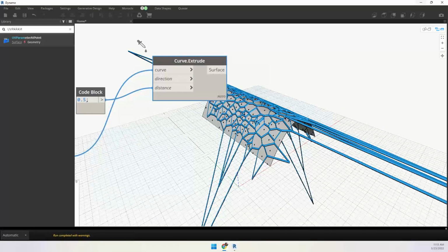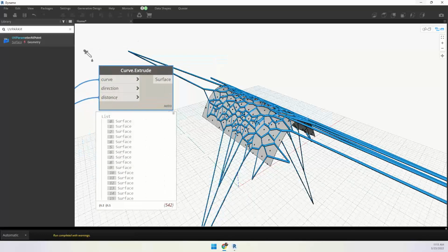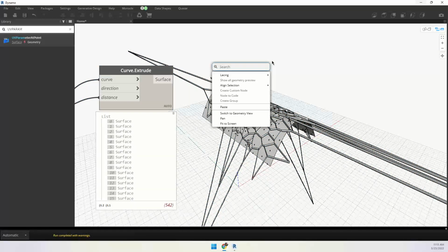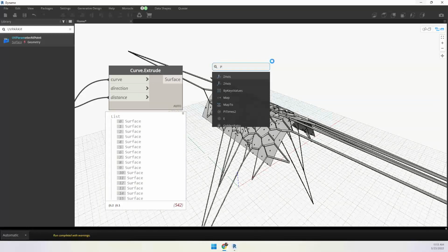How do I split this? Now I want to convert these surfaces into one common surface. This is what I hope you remember from what we did in the last sessions. If you want to split, you have to convert that into a single face itself, correct? Into a single surface. So how to join the surfaces? Type polysurface.